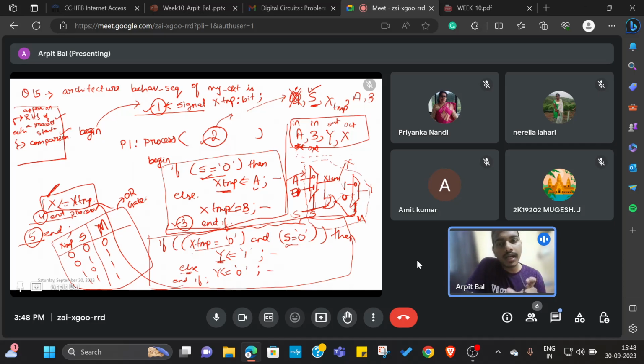You can write the 3 input ports and 1 output port of the mux, and that will synthesize a mux, right? But you can also represent it in the form of behavioral modeling that will describe the functionality, but it won't tell you directly that it's a mux, right? You have to figure it out from this code.